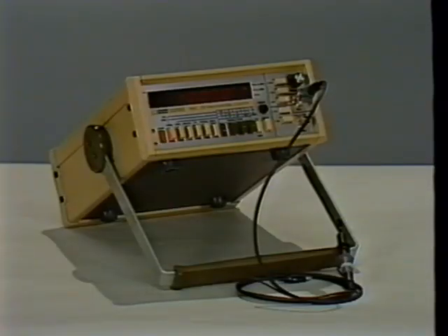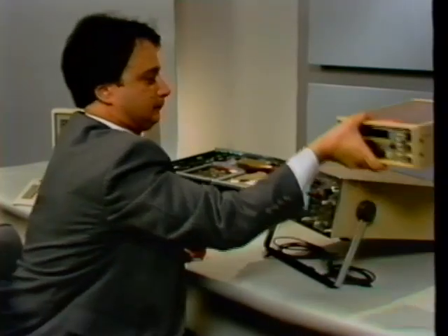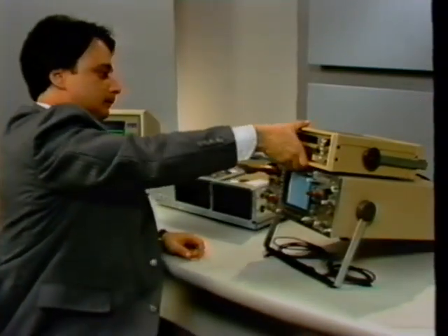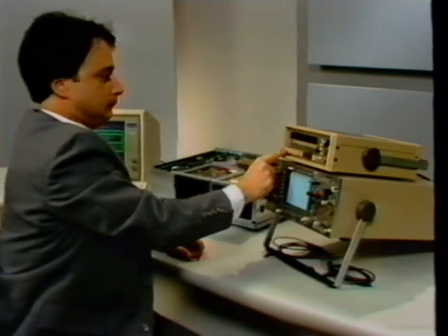In the previous section of this tape, we discussed the operation and use of the oscilloscope. Now, let's look at some other types of test equipment. This is a frequency counter. Its purpose is to time pulses or waves and report the results in one of several units. Frequency counters are used when a period or frequency must be measured more precisely than an oscilloscope will allow.